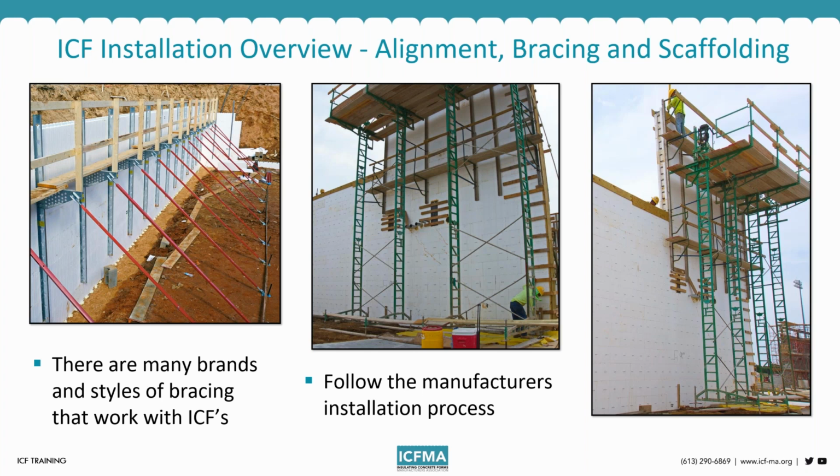But what an ICF bracing system is going to do is it functions as an alignment system. So once you get your wall stacked and secured, this works as a platform for you to continue building up your wall. And then once your concrete is poured, you're going to use the system to basically plumb and straighten your wall, so you have a nice finished wall that is nice and straight.